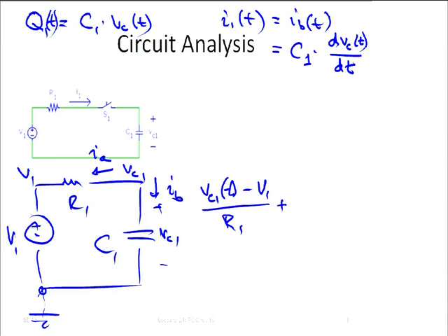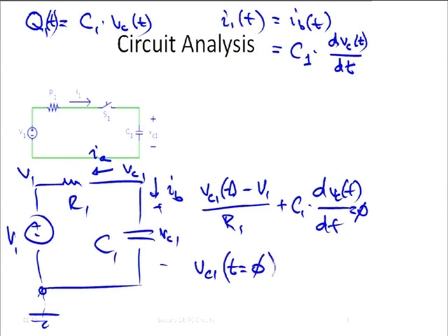Now, for those of you who remember the math and so on, can we solve this equation already? Do we know enough? What else do we need to know? Yeah, some kind of an initial condition or boundary condition, some point, right? Otherwise, we have a shift. What is the voltage initially? Well, I told you that initially the voltage is Vc1 of t equals 0 is actually equal to 0. Okay? So now basically I've told you everything. Right? The rest is math, and math you took in some math 1A or B or somewhere in high school, and you're done with that.